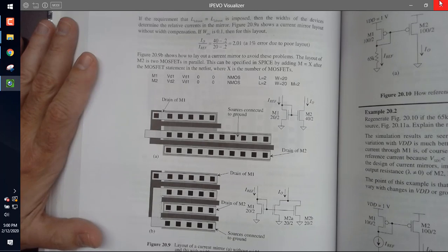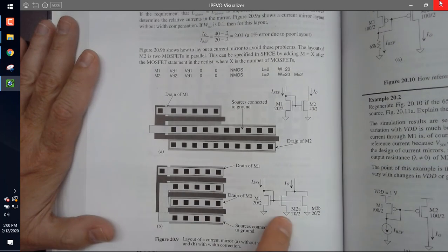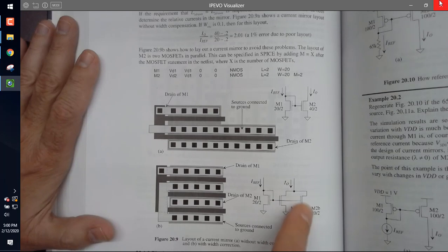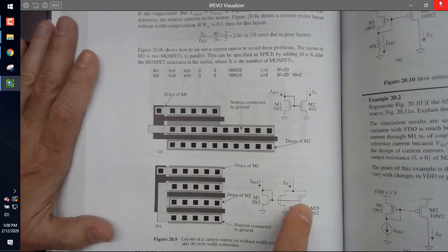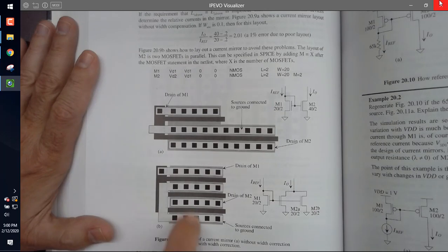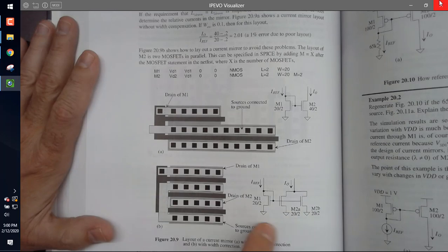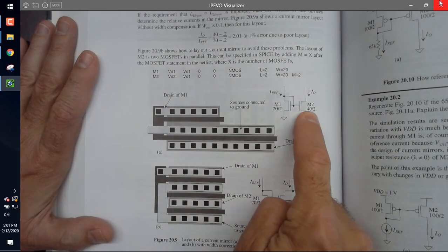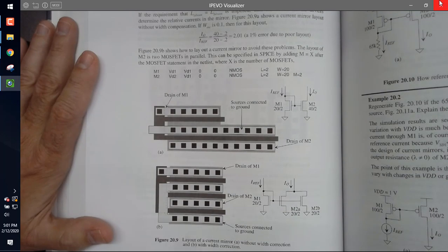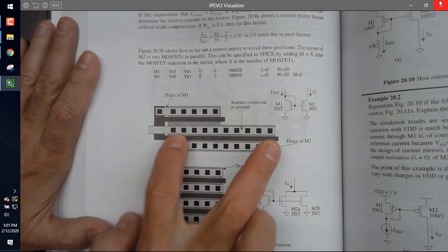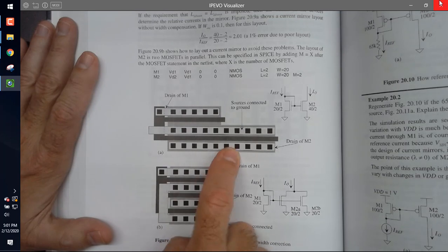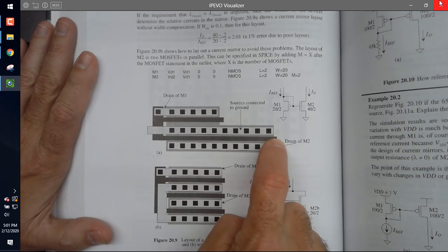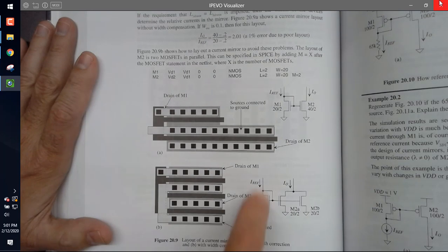So what you want to do is lay them out like this, where one of them has M equal to 2, so you've got the transistors where their sources and gates and drains and bodies are all tied together. This would be the layout for a good matching current mirror, where you would use M equal 2 here. Now you wouldn't draw it like this. You could, it would work, but you generally draw it with M equal 2. So this would be 20 by 2 or 20 by 2 M equal 2 if you did this layout, okay? So I'm assuming that you're using the same size devices. You're not simply doubling. These are more like the older technologies. You could get away with this because the oxide encroachment was tiny. And the newer stuff, everything's done like this, okay?